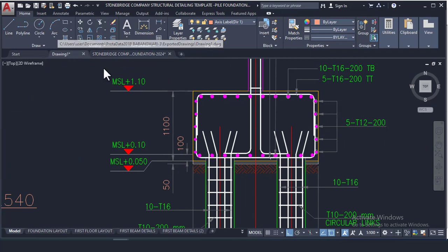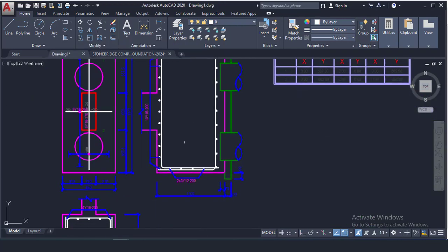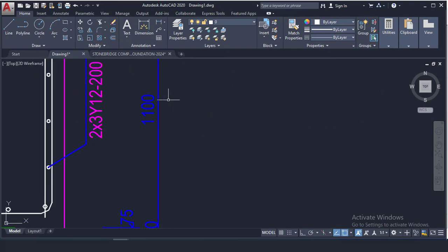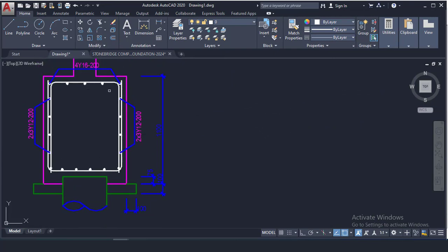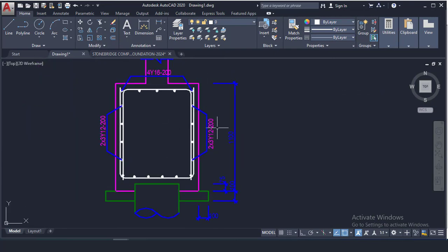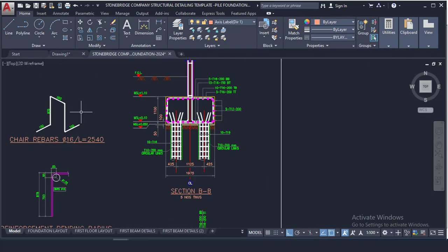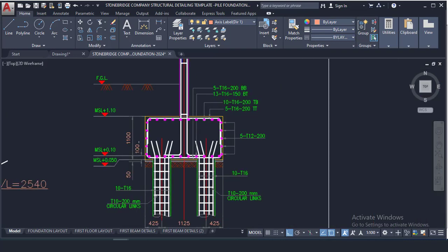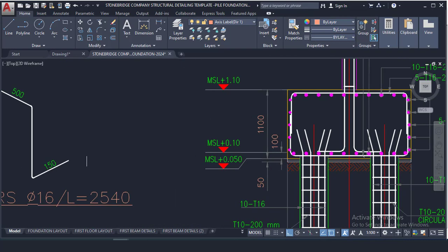From the design here, it is showing 1.1. There should be a shear reinforcement, which this prototype here didn't show, but this other one has to show the shear reinforcement, because at this depth you are meant to provide shear rebar.